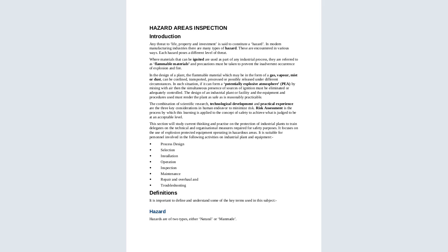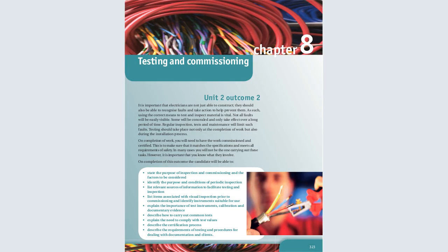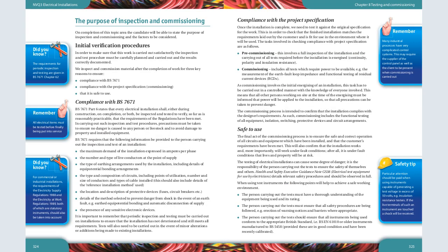Then for code number 2, just some few points like absence of proper earthing at socket outlets, absence of main protective bonding.